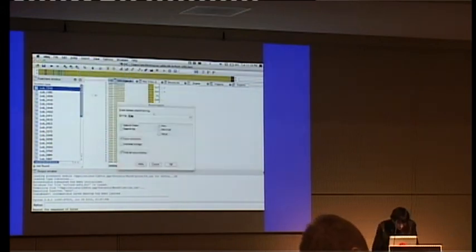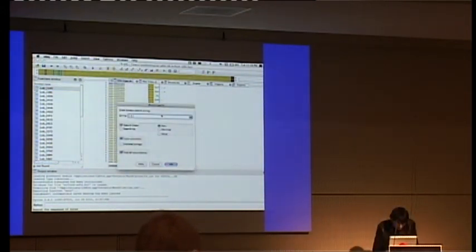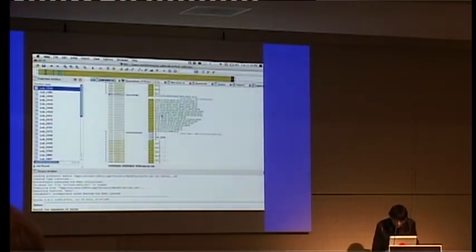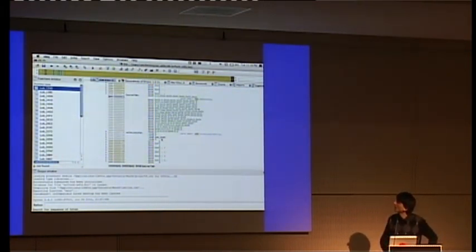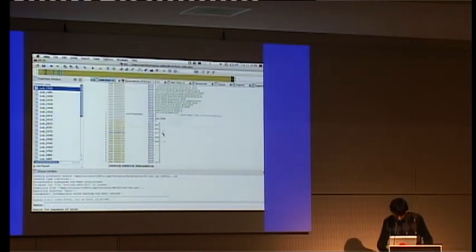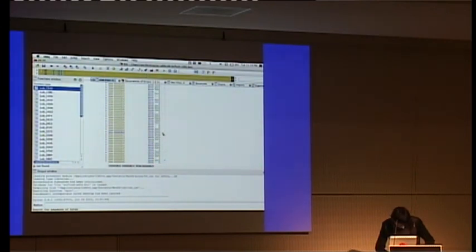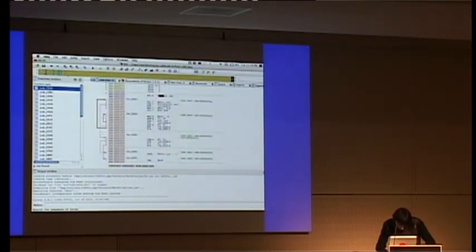The thing to search for, I think, is this sequence. So this is the keylog, the translation table. And if you go a little bit down, you'll start seeing code, hopefully. So this is the entry point for the embedded controller firmware.